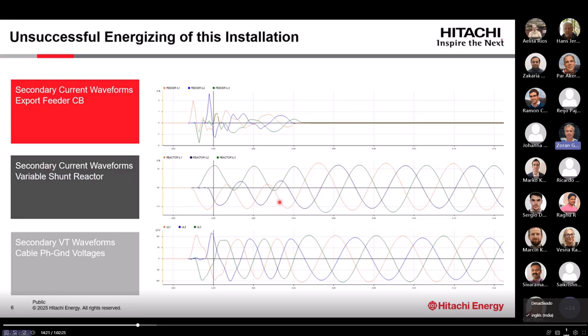Once you energize the cable, you store the energy in the cable capacitance. Once you open this main breaker, you have stored energy and almost no resistance. Therefore, this will start to oscillate. You'll have LC oscillation, which will last for quite a long time. And during this time, all protection which measures these signals will sooner or later go crazy.